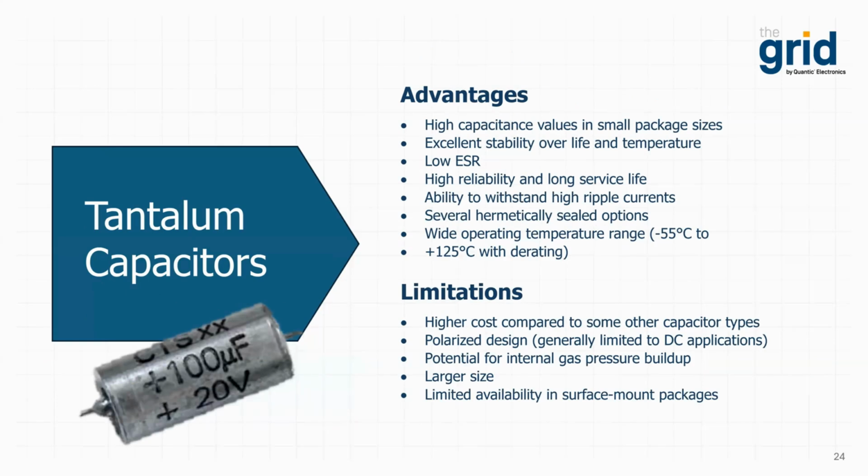Now, avionics designers select wet tantalum capacitors for their combination of high capacitance and reliability in the demanding environments typical of aerospace and avionics systems. Their highly desirable SWaP, or space, weight, and power optimization advantages must balance with their cost. Some advantages include the fact that they have high capacitance values in really small sizes. They perform very well, with excellent stability over life and over temperature.